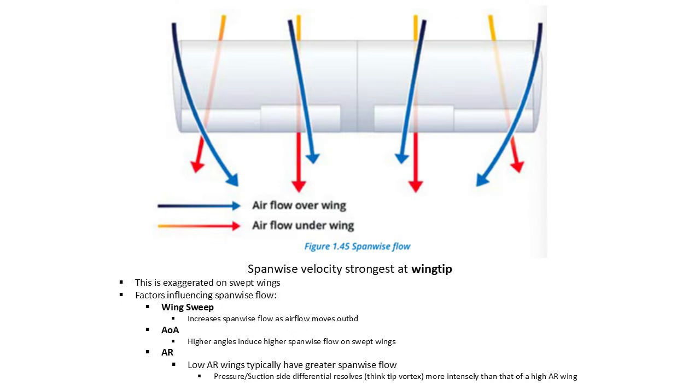I also mentioned a minute ago that the magnitude of the wing-induced spanwise velocities generally increase as we move outboards towards the wingtip. This means that to have the most effective winglet, it should be placed where the induced velocities are the highest, which is at the very end of the wing, of course, to increase the effective angle of attack on the winglet, and therefore increase the forward-oriented resultant, quote-unquote, thrust vector.